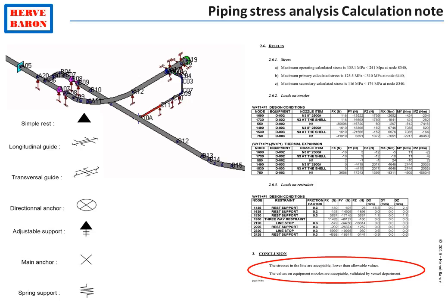And then the piping support engineer checks that the stress level in any part of the line is below the maximum stress level acceptable for the material of construction of this line, and that the maximum efforts at equipment nozzles are not exceeded, which validates the routing and supporting of the line.